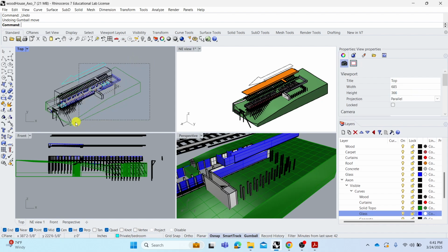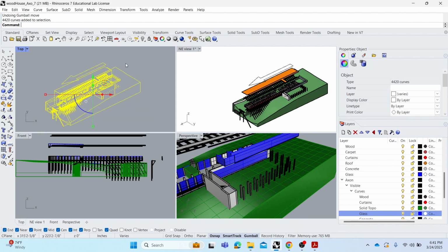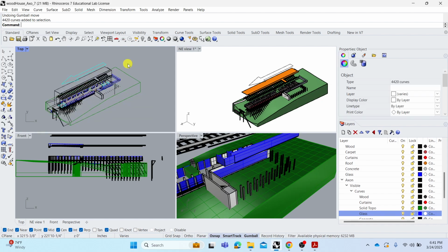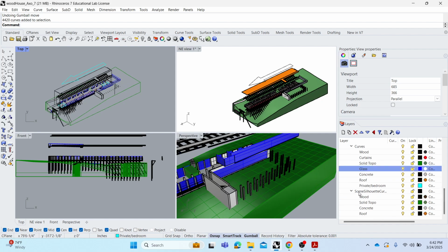What I'm going to do now is select all these elements. Actually, do I want to do anything else before I export? I know a couple people are getting really confused exporting layers into Illustrator, and that's because Make2D creates many parent layers.